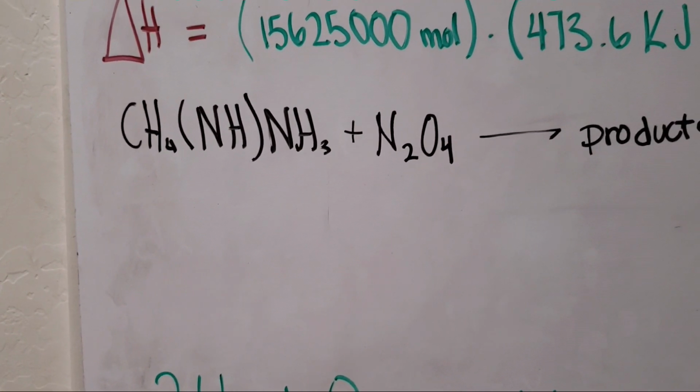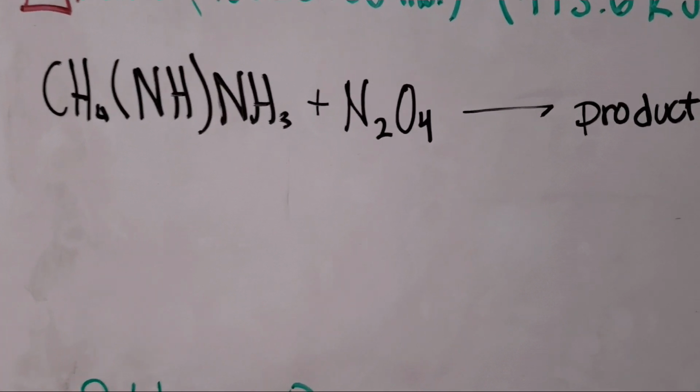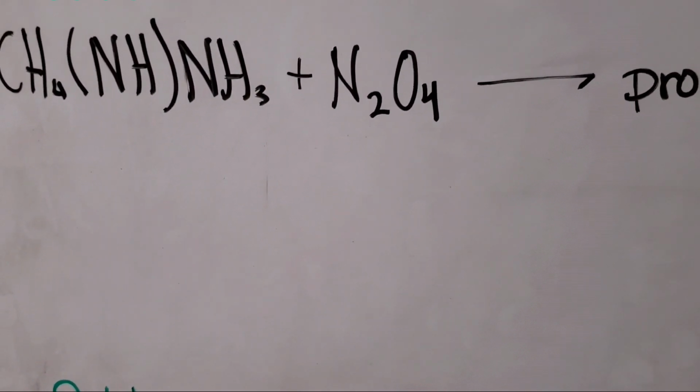Now I'm just going to mention real quick a hypergolic reaction in which the chemical reaction requires no spark plug. The chemical reaction is so volatile that just when the chemicals start mixing on their own, they will just start burning right away. Let's take a look quickly at an example of that. So here in black, this chemical reaction is monomethyl hydrazine mixed with nitrogen tetroxide.